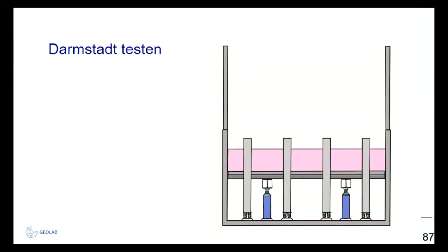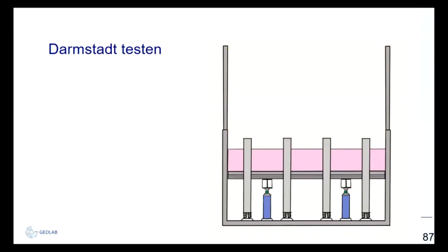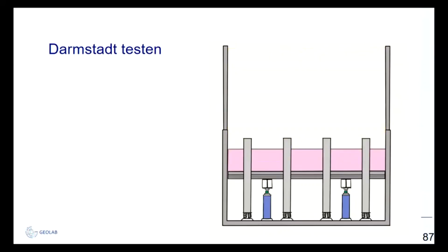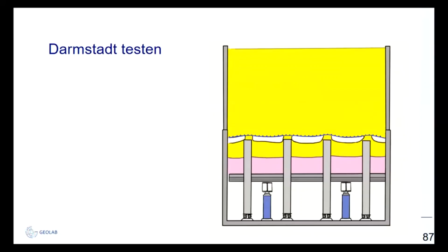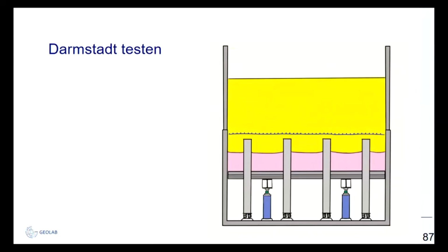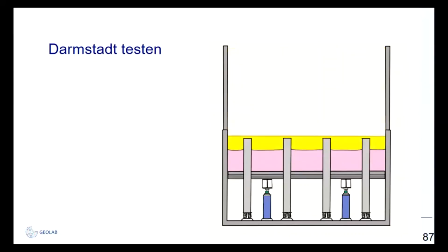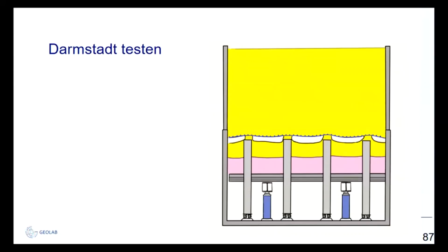And this is what happens in practice in many cases, because you do not lose your subsoil support immediately. But after a while, it often happens because consolidation occurs underneath the piled embankment due to the weight of the sand underneath the reinforcement, or for example, due to groundwater level changes. For example, due to some construction activity close by where the water is drained out.